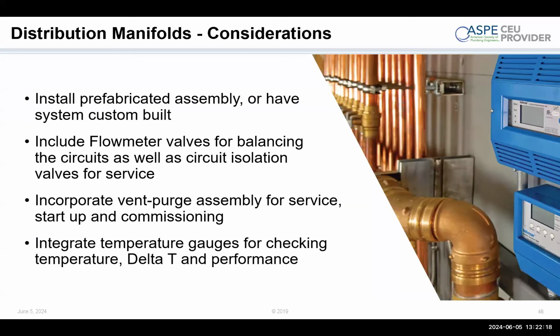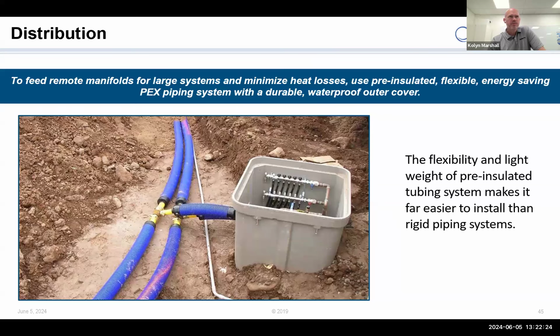Is there any considerations for above ground manifold like cabinets? Not from my perspective. Really, my requirement on a manifold enclosure is that it is free from the elements. It's not sitting in water, so it has drainage, and it is sized to handle whatever loading is on top.